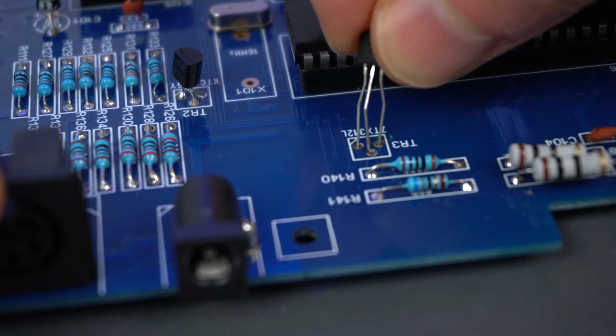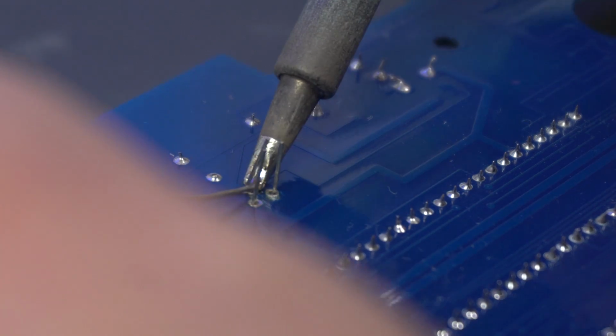We could definitely get the BC547 to work, but it would require at least one extra resistor and one capacitor. And I'm sure we could put those on the underside, but it would just look a bit ugly. A tidier approach would be to use one of the other two transistors since they don't need any extra components. I'll pick the 2N7000 because it's the most common of the two transistors.